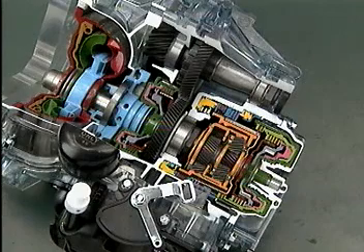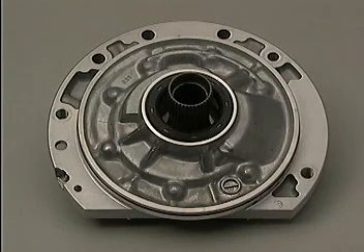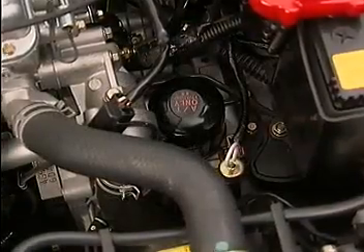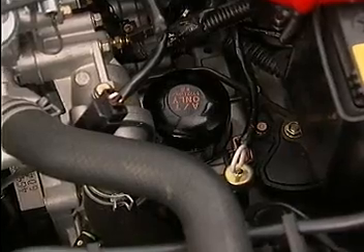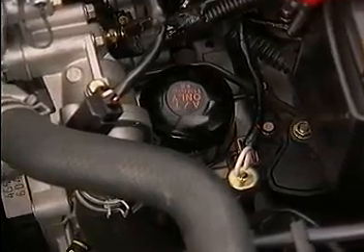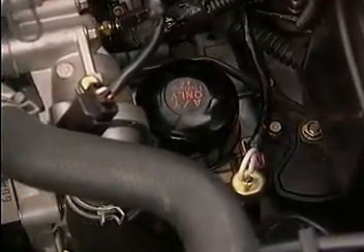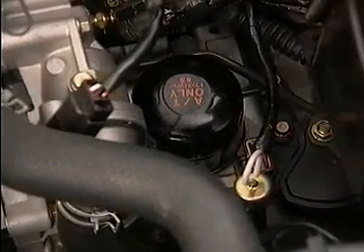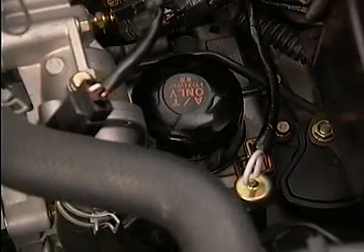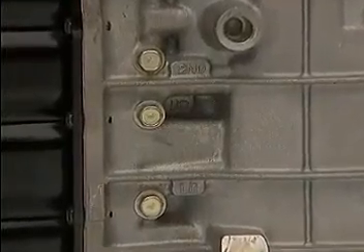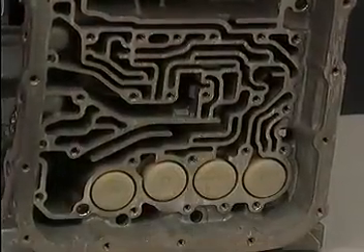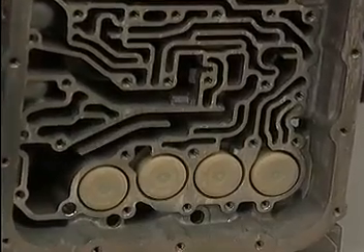The hydraulic circuit consists of a front oil pump which is not serviceable and must be replaced as an assembly. 2 oil filters, which we saw in Part 1, consist of a spin-on external subfilter. Never install an engine oil filter here. And a main filter, which is not replaceable, except during a complete transaxle overhaul. Pressure ports for servicing, and 4 accumulators which help control the quality of the shifts.